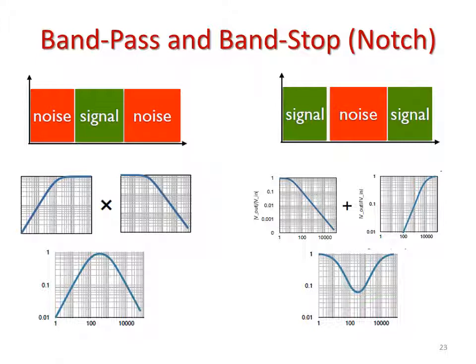Band stop filters are a little less found in industry, but sometimes they are an important part. A band stop filter or a notch filter allows low frequencies through, will remove a middle selected frequency, and then allow high frequencies through again. So this one is specifically for if there is a specific bit of noise in the room at a specific frequency that you don't want impeding some other electronics, and you want to listen to the other electronics. You use a notch filter. Sometimes this is for when you're trying to make sensors to analyze ambient data.